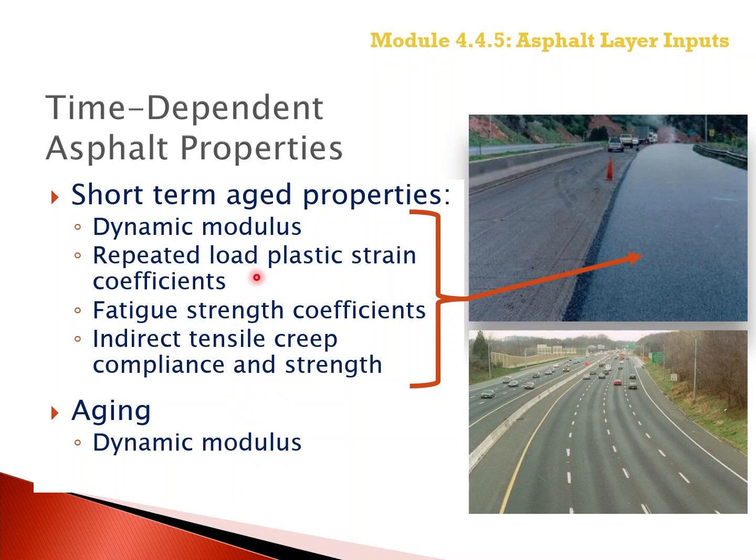So at the beginning, at the time of construction, the asphalt mixture properties entered into the PMED software are short-term aged properties for the response and strength coefficients for the transfer function.